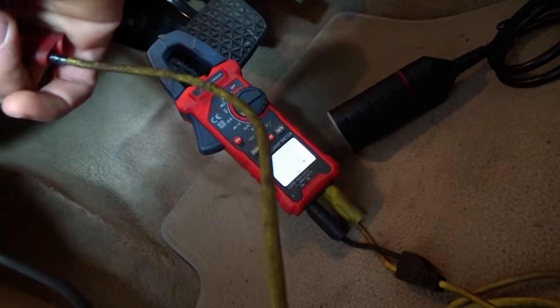So in this case, the ohm meter didn't show us anything conclusive. Now, the customer said that this problem is intermittent. You know, the car remembers the faults, but it's not necessarily a permanent fault. So what I want to do now is hook up an oscilloscope to both CAN high and CAN low, pins 12 and 13, and take this car for a test drive.